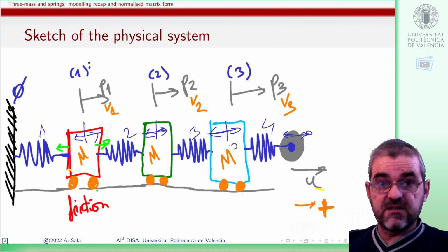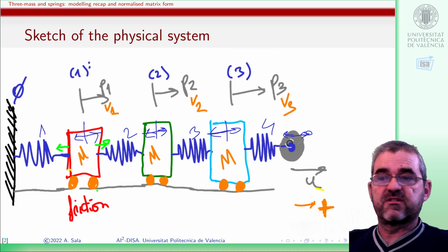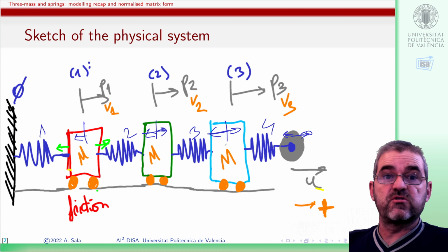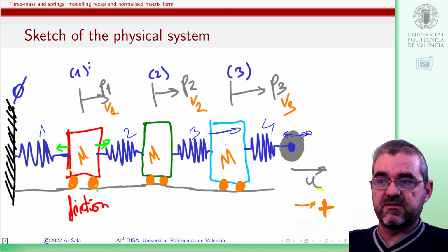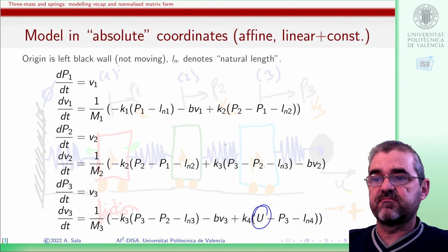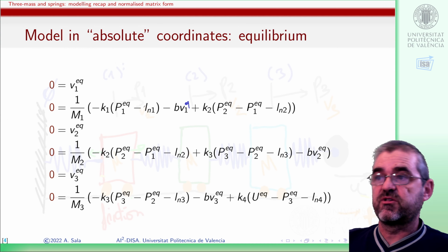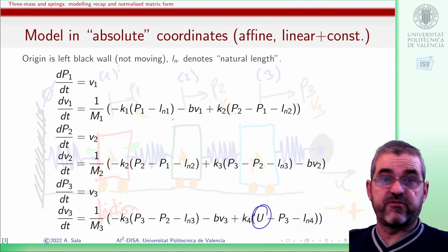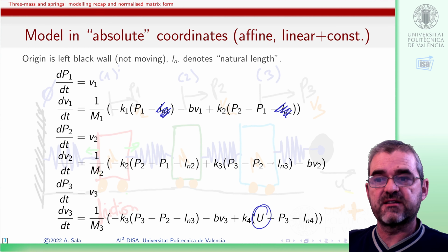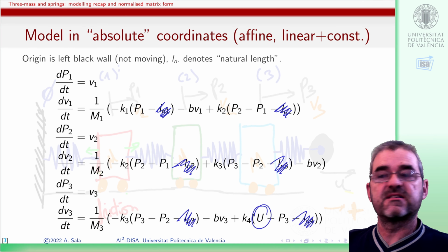Then if this is my actual engineering problem, displacements, vibrations around the equilibrium points, then I don't actually care what the actual equilibrium is, in the sense that if I assume incremental variables in linearization, then natural lengths have no increments, they are constants, so constants disappear in the linearization, in the incremental variable reference system.